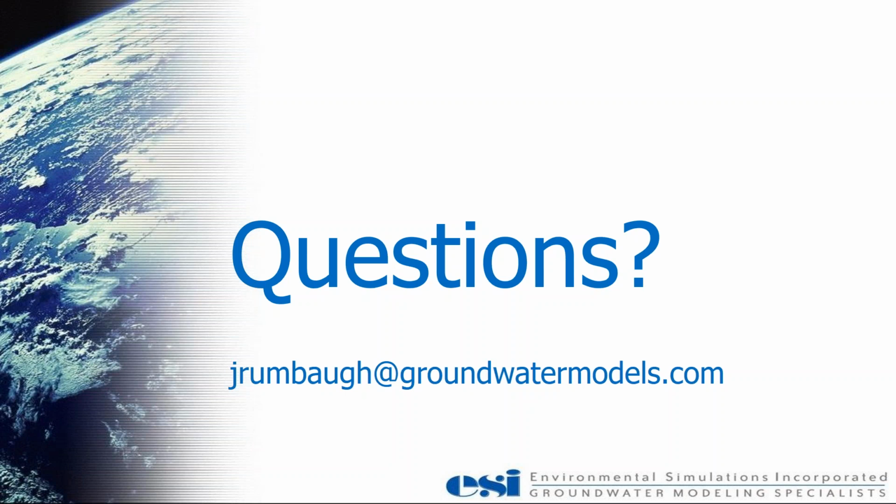Now, let's see. Next question. Is there an unsaturated option available in MODFLOW 6? No. The closest would be the UZF package, and that's not really unsaturated flow. I mean, kind of is, kind of isn't. It's like a one-dimensional unsaturated approximation within the vadose zone. It's not really unsaturated flow the way MODFLOW USG and MODFLOW Surfact do it. So no, they don't have that.